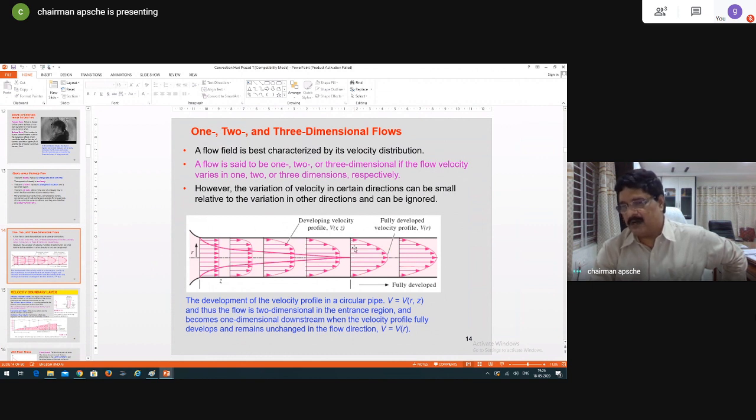center of the tube, are you watching? The velocity vectors are bigger and bigger. That means the magnitude is higher and higher, meaning velocity is increasing. And similarly, from the other side, velocity is zero at the surface, slowly the velocity is increasing, and finally, at the center, where the boundary layers are merging, the velocity will be the free stream velocity.